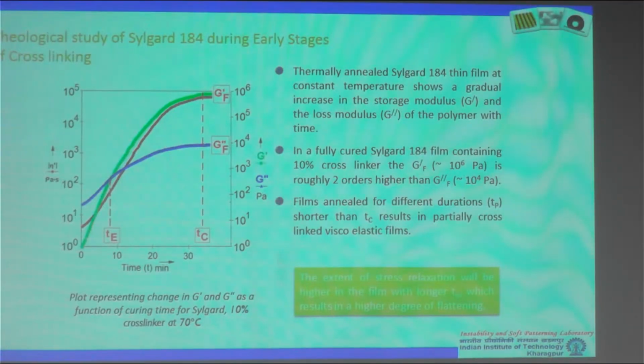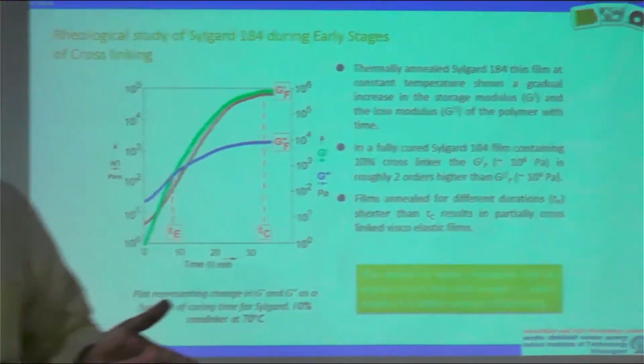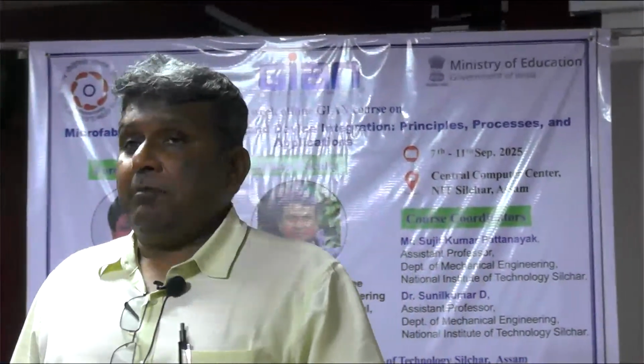The energy that you use to deform it remains entirely stored within the matrix itself. Now think of a material which is partially viscous, partially elastic. If you apply some energy from outside to cause deformation, part of the energy will remain stored within the elastic matrix, and part of the energy will dissipate because it exhibits some viscous properties.